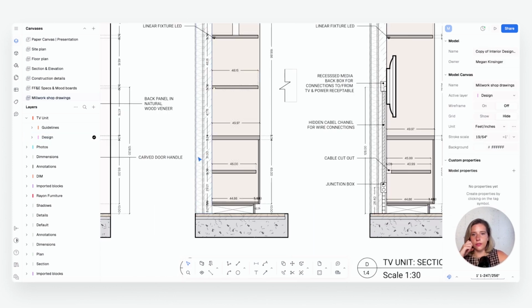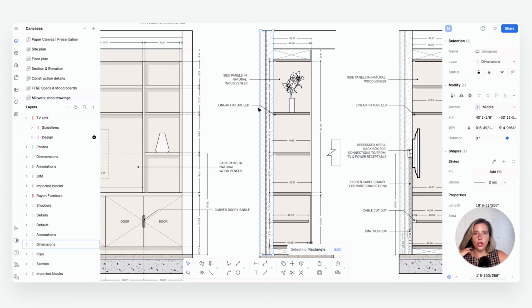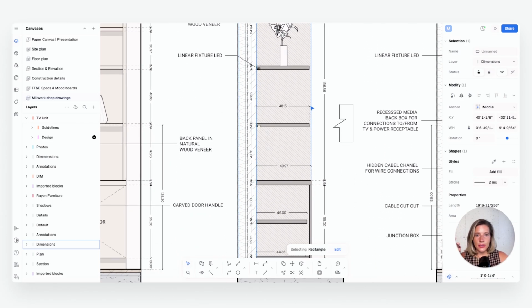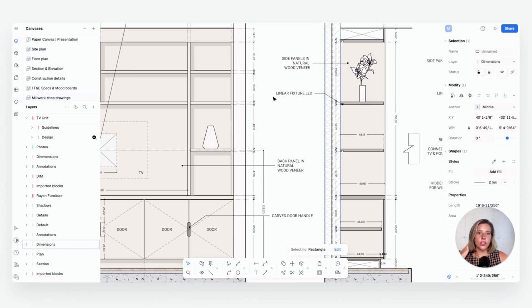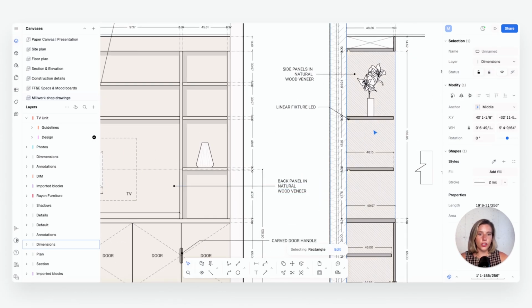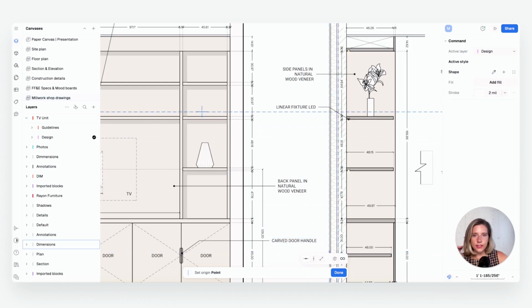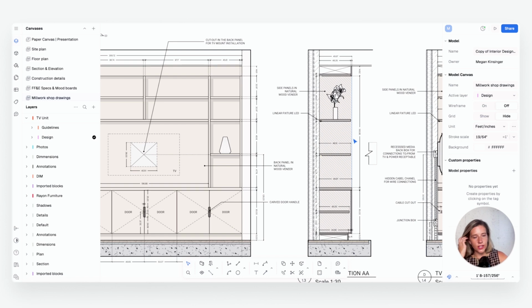And then the same goes here for the vertical walls as well. You can see all this section stuff is the same kind of thing that we've already done. This is also a good thing to note for your sections when you're creating them after you've created your elevations. Super helpful, again, to grab those guidelines down here. If you go to your guidelines and then horizontal, you can see that if you just start placing those, that really helps drive what you're cutting through in your section. It eliminates the guesswork, and it makes sure that everything is aligned.